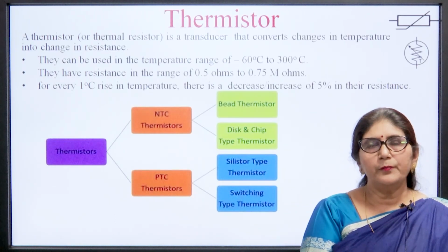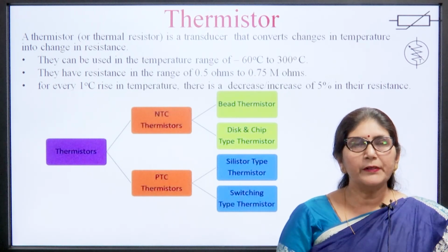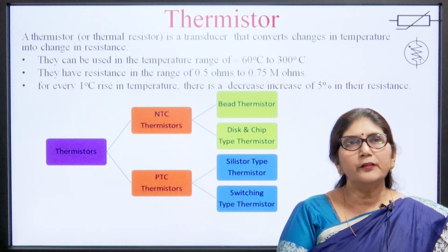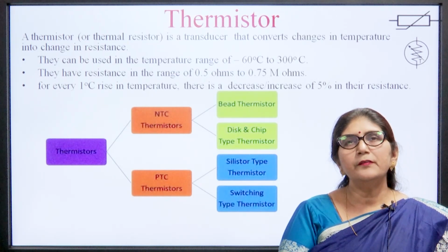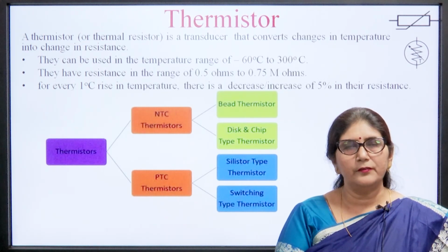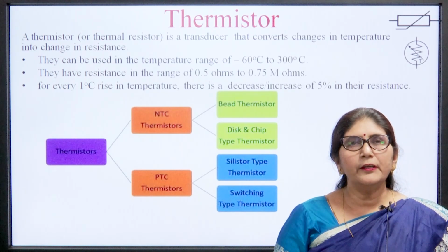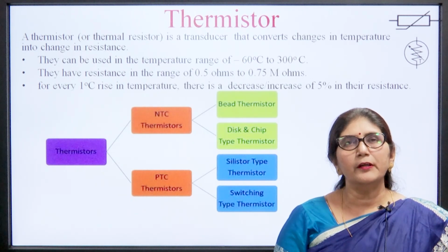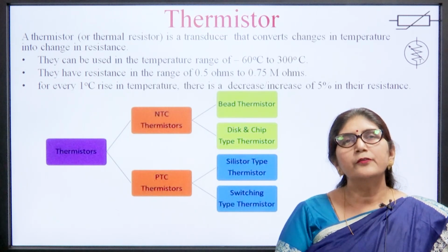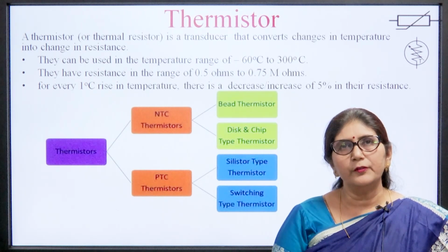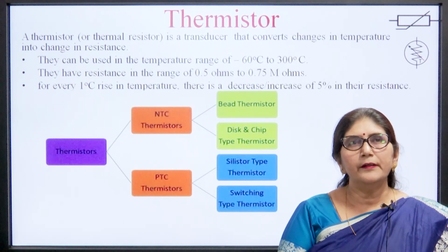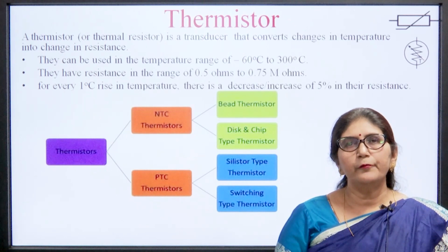So, thermistor is basically an abbreviation of thermal sensitive resistor. So, that is why it is known as thermistor. Thermistor is a transducer that converts change in temperature into change in resistance. Since it requires an auxiliary source for conversion of change in resistance into change in voltage, it is a passive type of transducer.